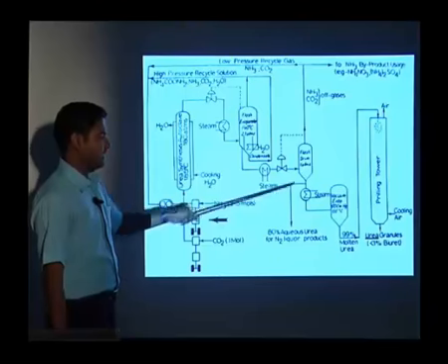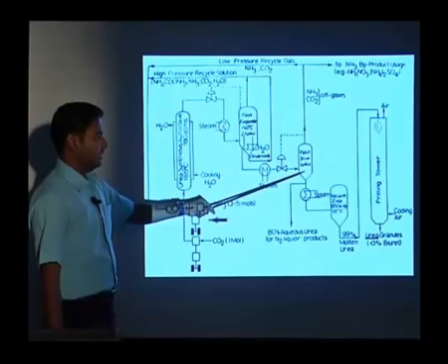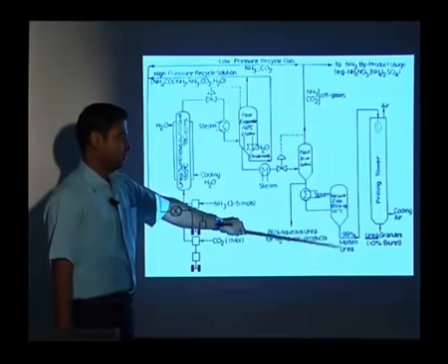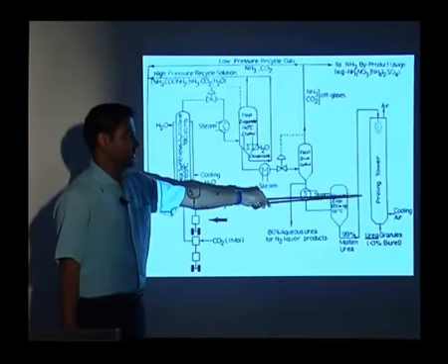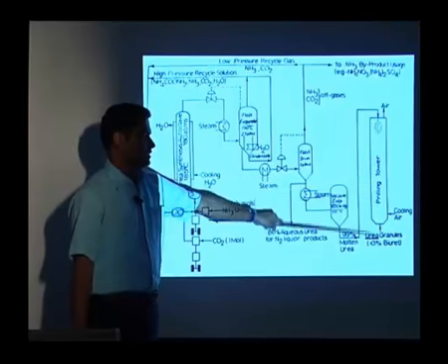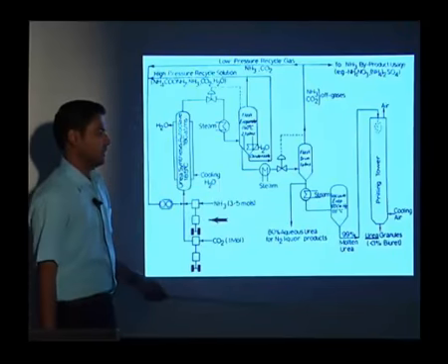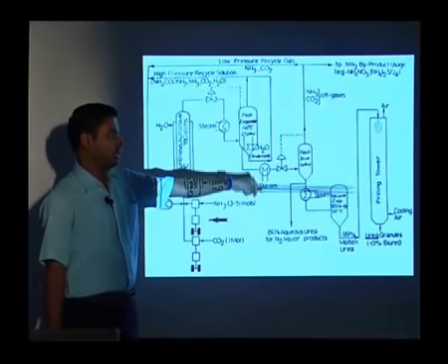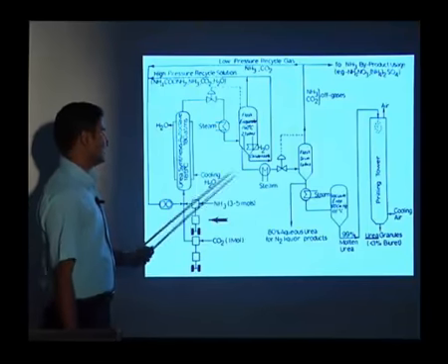After decomposition of the ammonium carbamate, what we get is urea. So urea we can either have in aqueous form, that is 80%, which we feed to the liquor, or we can have another vacuum evaporator which will separate, and we can have the molten urea. Then this urea is sent to the prilling tower, where it is sprayed. With the help of air it will be solidified. These prills we can bind into urea granules, and they should have less than 1% biuret. So the molten urea, with the help of cooling air, we prill by spraying, and we get urea granules which contain less than 1% biuret.